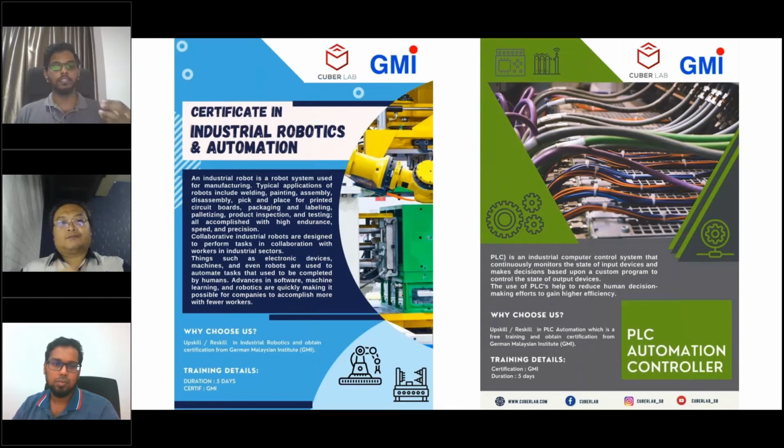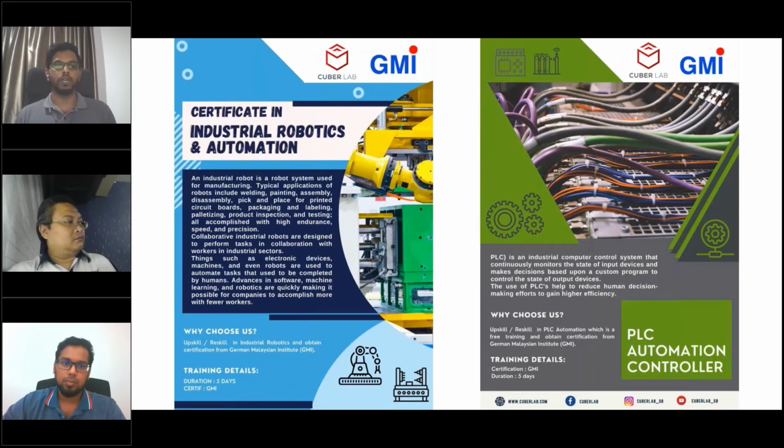In oil and gas, the 6-axis industrial robot is also being applied. But the robot must come with a particular certification such as ATEX, which is explosion proof. This kind of application is still being implemented in oil and gas, but it depends on what kind of application they are looking at. It might be related to an oil and gas parts production facility, or is it really on an oil and gas platform? I think there are new robots such as Spot Mini being used on oil and gas offshore fields, where it can move and do operations and so on.